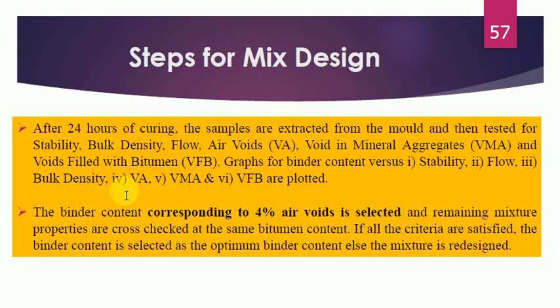Mainly we have to conduct the test for calculating the bulk density of the mix, and parallelly we can calculate the air void, and the test by using the Marshall method is basically the test for stability and flow.